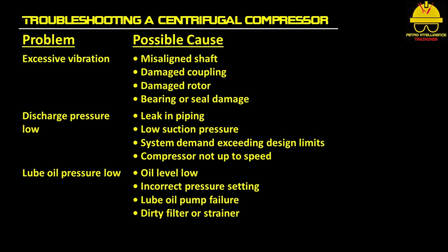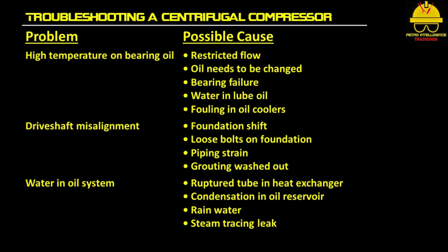If lube oil pressure is low, there might be low oil level, incorrect pressure setting, lube oil pump failure, or dirty filter or strainer. If there is high temperature on bearing oil, there might be restricted flow, oil needs to be changed, bearing failure, water in lube oil, or fouling in oil coolers.